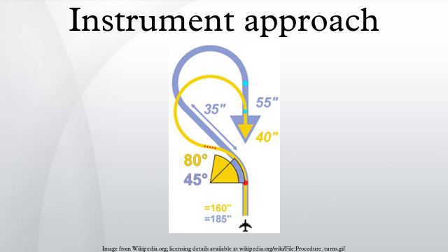Teardrop procedure turn. If the controlled airspace is extremely limited, a teardrop may be used to reverse the direction of the aircraft and permit the aircraft to lose altitude. This procedure is shaped like a teardrop, hence the name. It typically consists of the outbound course flown at a 30-degree angle to the reciprocal of the inbound course, and then making a 210-degree turn to intercept the inbound course.